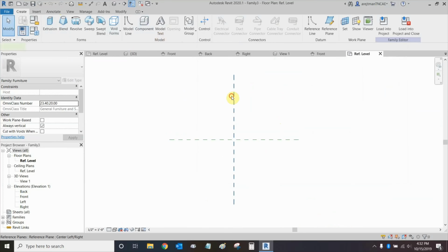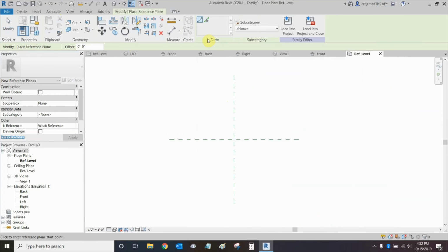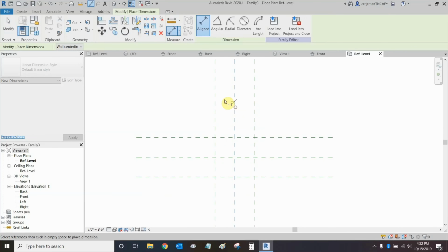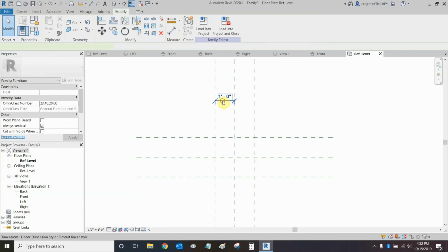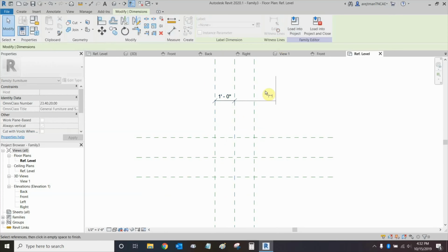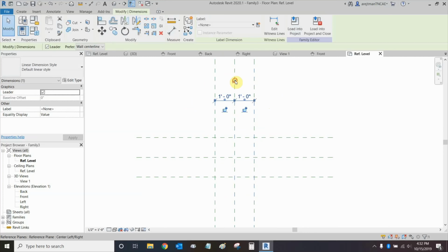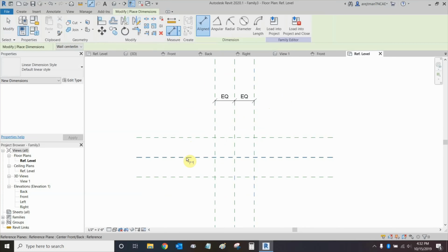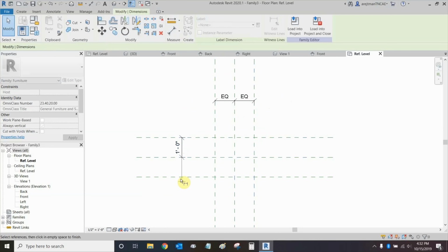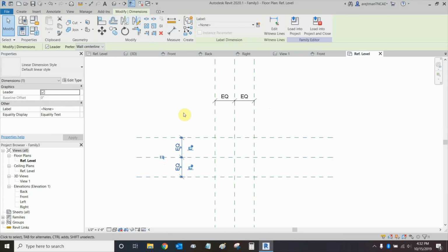But first, of course, let's make the reference planes for it. So pick lines, offset of 1 foot. This is arbitrary. You can offset it to anything you'd like. I just want mine to be pretty even along the center, so I'm saving a little bit of time. We're going to equalize it just like we did with the display case itself. Edit witness lines, equalized. Once more here, from major to minor. Edit witness lines from major to minor and equalize.